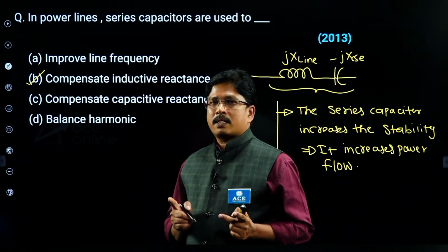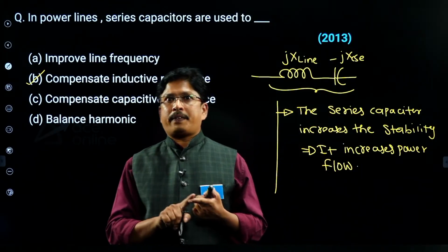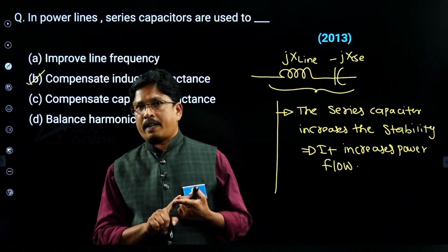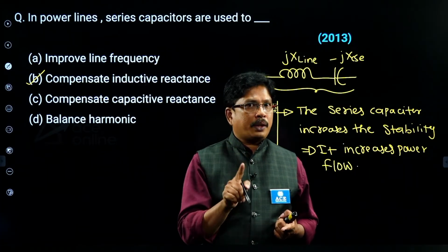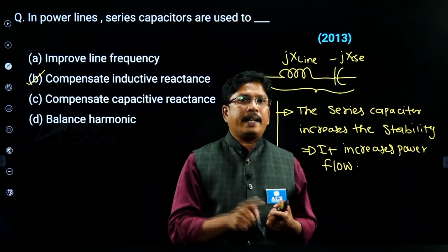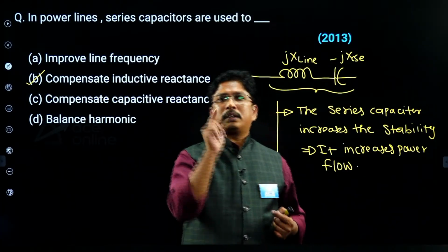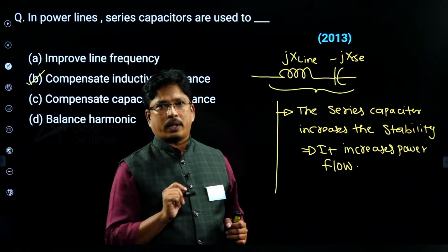And also students, for leading loads or under no load condition, the series capacitor can eliminate the Ferranti effect also. Remember everybody, not only the shunt inductor, the series capacitor also can reduce the value of the Ferranti effect under no load condition.